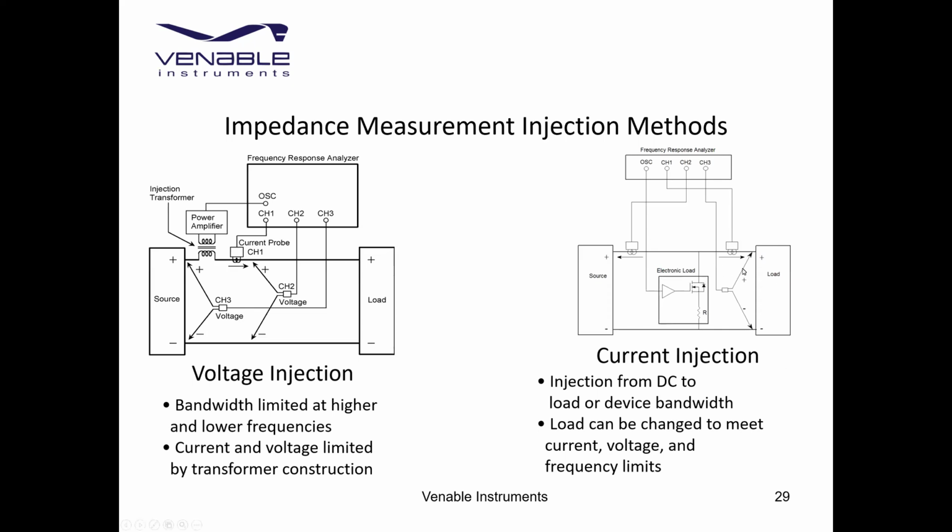Once you're up in the megawatt range, you basically have to inject a square wave using an IGBT into a high power water cooled resistor, or a utility grade resistor as your load, depending on what kind you're using. And you won't burn up the IGBT. It's either full on or full off, but the injection method does work. Even if you're using a square wave, you will still get the correct impedances.